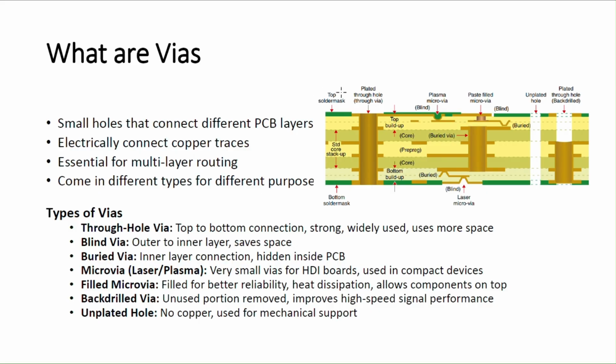For example, this complete through hole wire will be connecting from top to bottom, and it will be connecting between internal layers. When you define this plated through hole wire, you will define top layer, inner layers and bottom layers. Once you place this, it will automatically connect to top layer, inner layer and bottom layer if the electrical nets are the same.